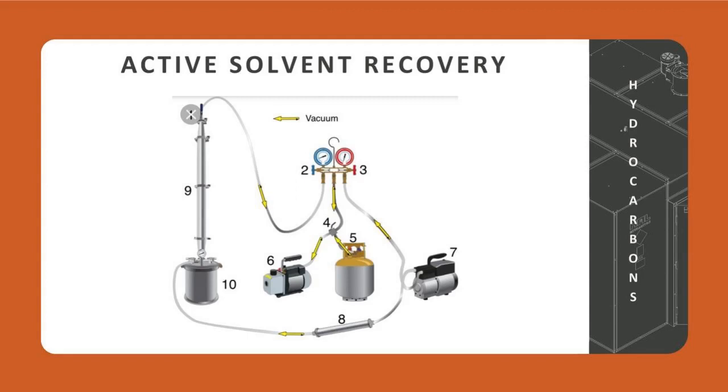And so you're moving the solvent from the tank into the system. And then conversely, your recovery tank is going to be placed in a cold water bath, which creates that negative pressure differential, will encourage the solvent to move through the system, and allows you to recollect the solvent after a run in your collection vessels. After, of course, you have removed the cannabis extract from the closed loop system.